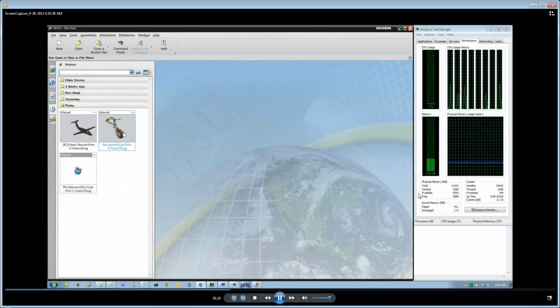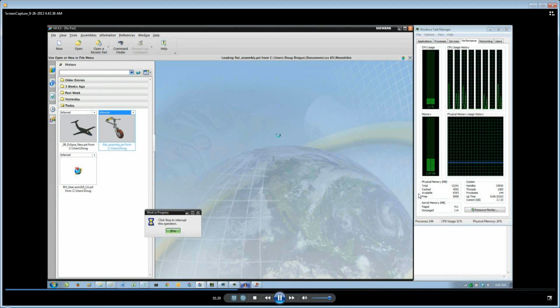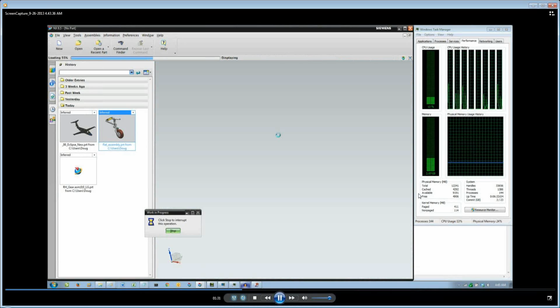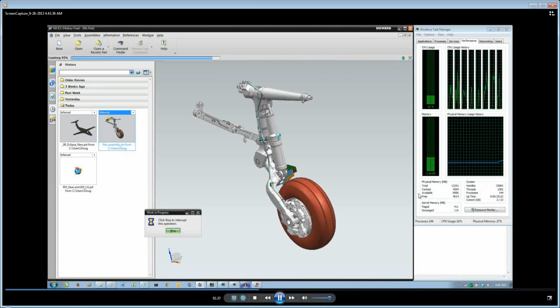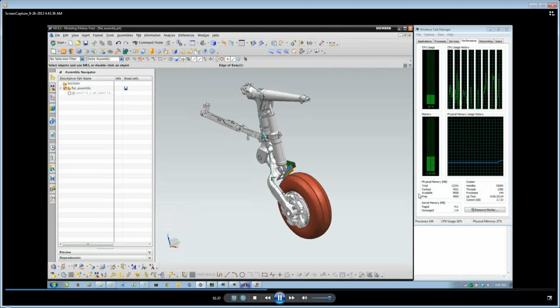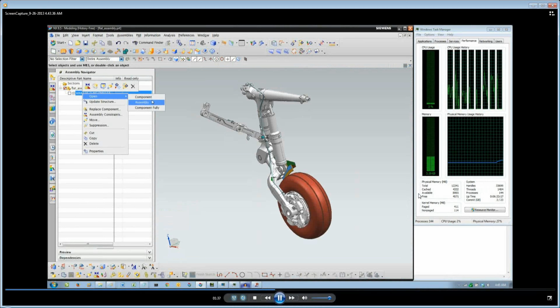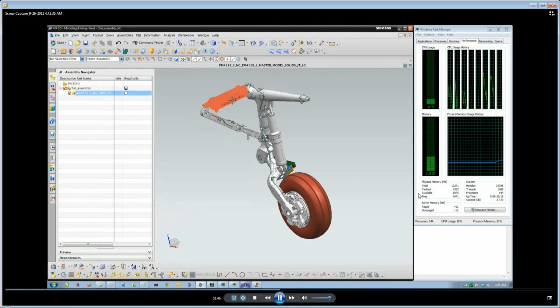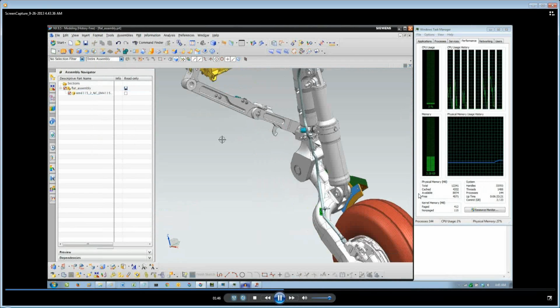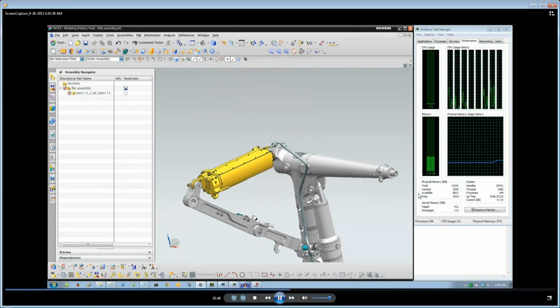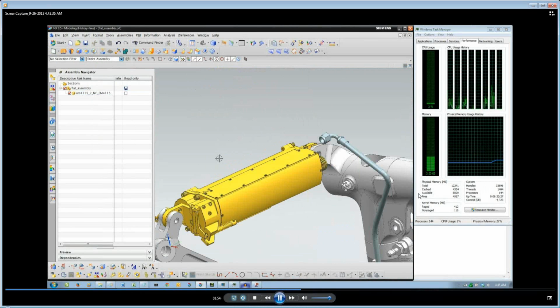And now we'll open up a monolithic one. It's the same exact assembly, only just done differently. So here's all the parts. We'll wait for these to render. Now you can see that the hierarchy's gone. There's still that vendor part. So that lightweight body's still there. Still take a look at it. It's still a component. But the big difference is the other components aren't listed in the assembly hierarchy anymore.